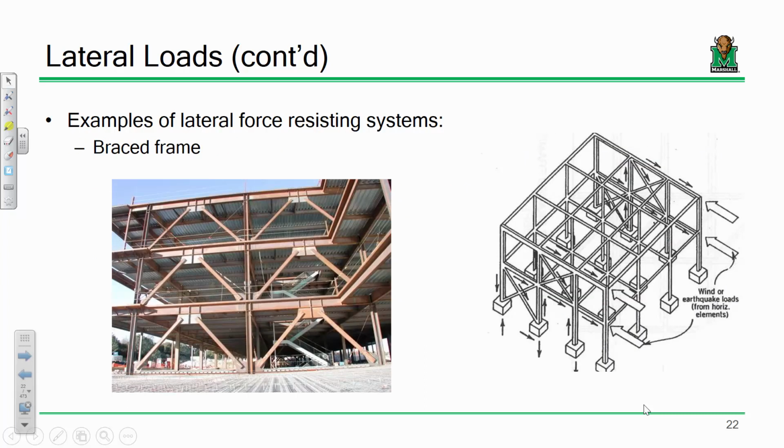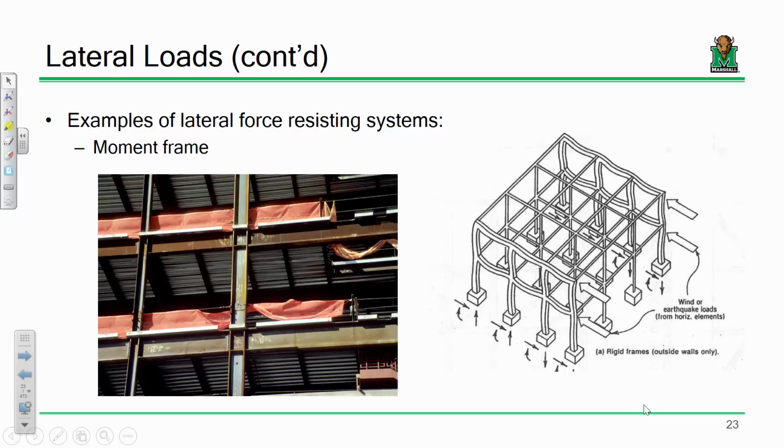For buildings, we have really 2 primary classifications of systems, either a brace frame, where we're physically installing braces in a building to hold it up during a given lateral event, or a moment frame. Moment frames are where we use more rigid connections and deeper sections along a given frame line to keep the building upright. Moment frames allow for much more open access. You don't have a big brace in the middle of the building, so the architect's happy and it makes the owner happy, and it sometimes is necessary given the ductility requirements of the structure,